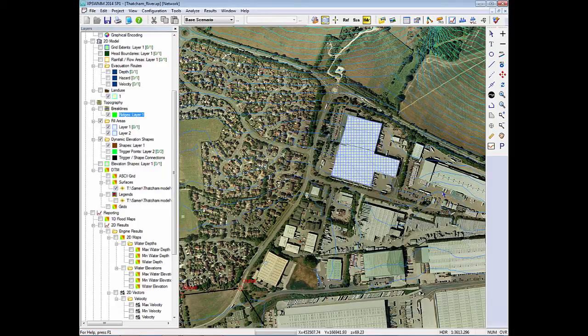But the most accurate way to model something like that will be flow constriction. This is recommended when you have a fussy boss, and he's very, very accurate. So this is the accurate way. You can draw the polygon, full area, similar to what we've done.